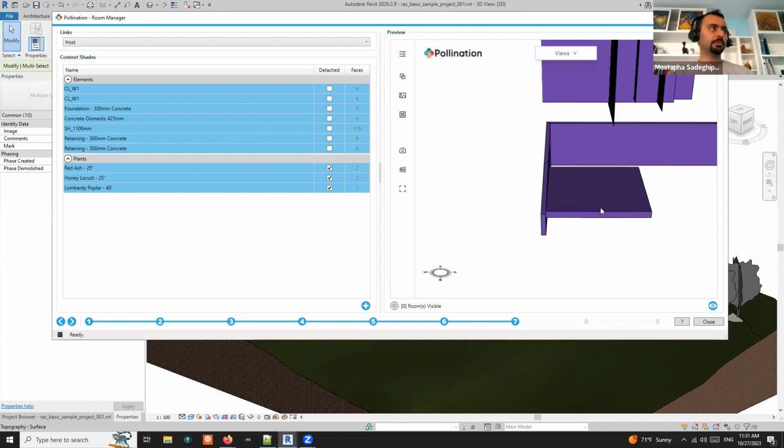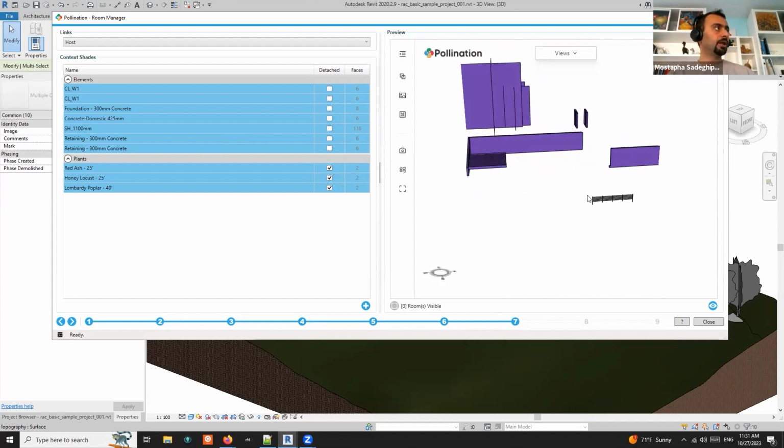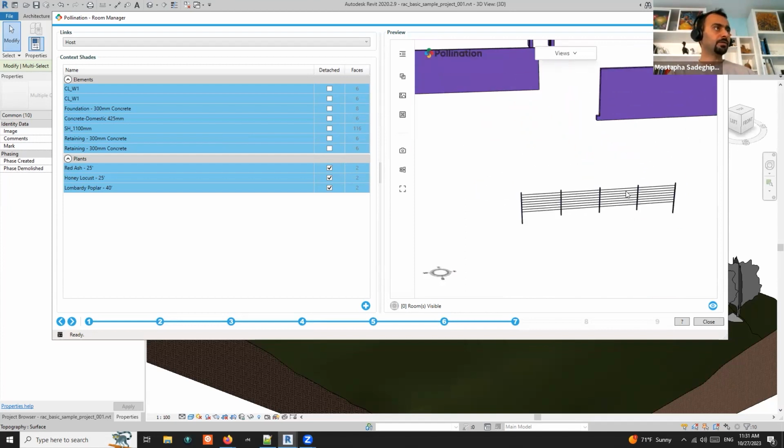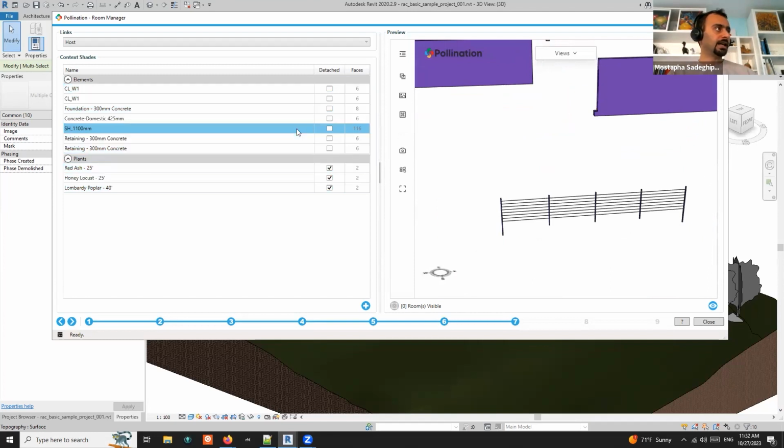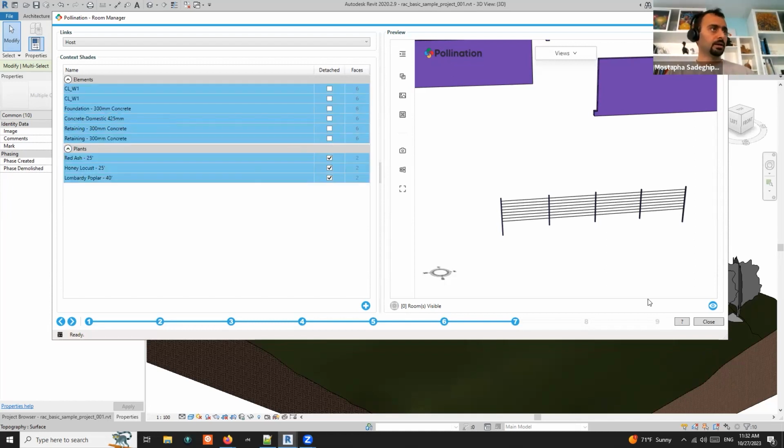For the other geometries that we can get the real geometry, we really try to get the geometry. Here, one thing that I would always check is if you have something like this, and it's adding 116 faces to your model. If you're using this for energy modeling, you better not include it, right? You can always right click here and remove it from your selection. So now I have all these faces here.